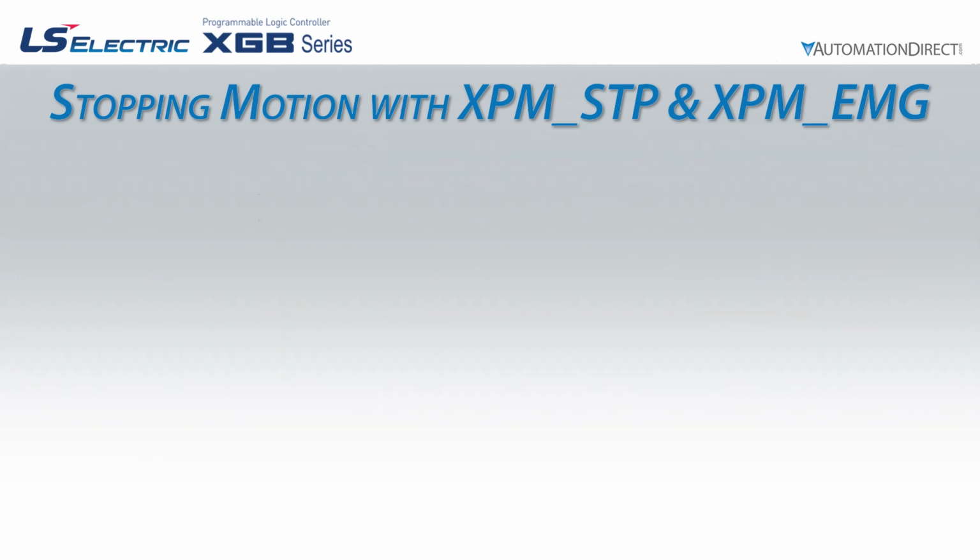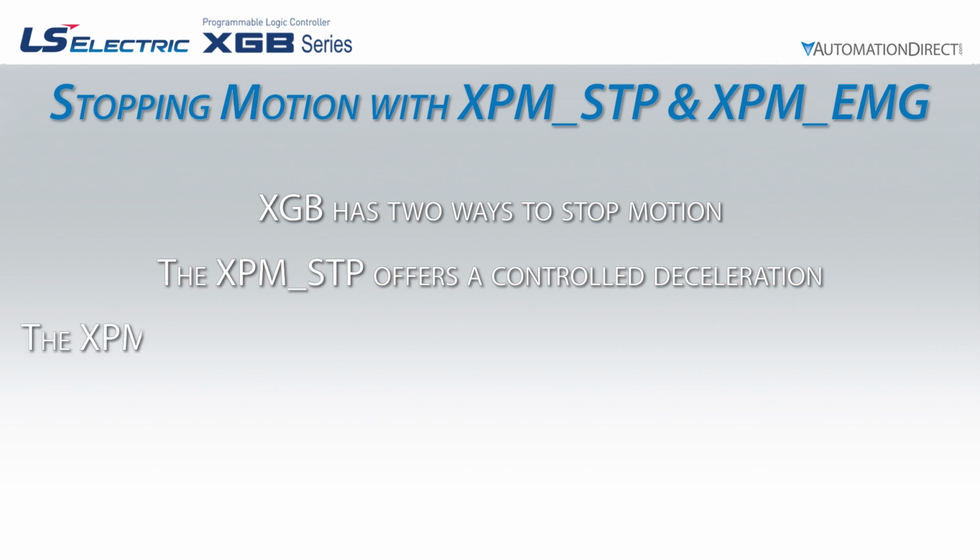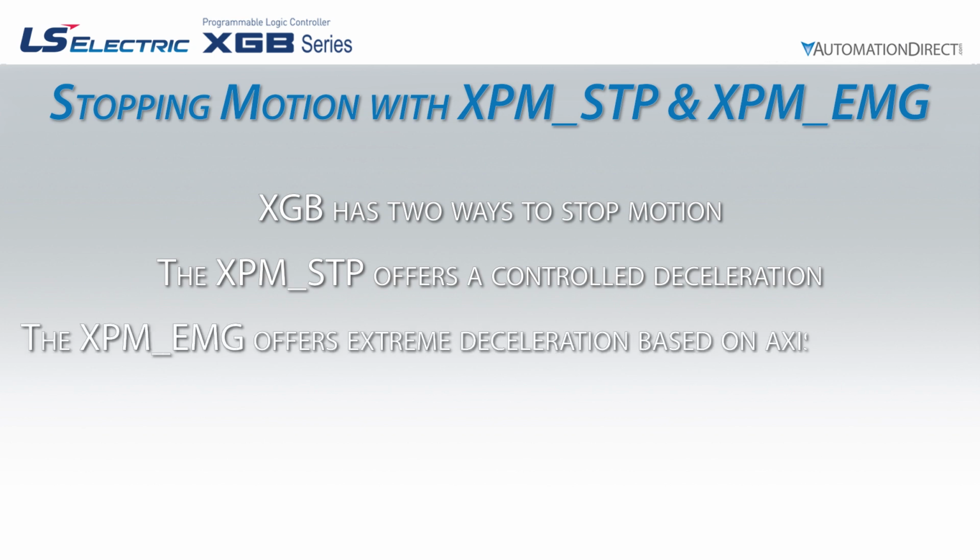As we see here, it is easy to stop motion with the XGB PLC. We can use the decelerating stop for normal motion profiles, or execute a much faster emergency stop that will also fault our axis, preventing immediate restart. Regardless of what our application requires, one of these two stop function blocks can do the job.